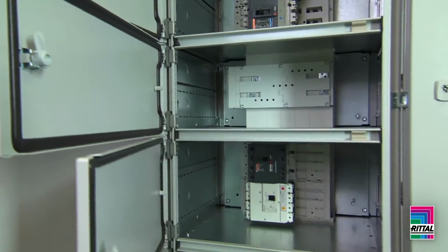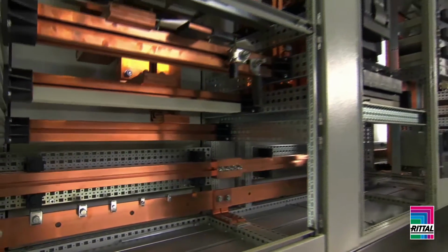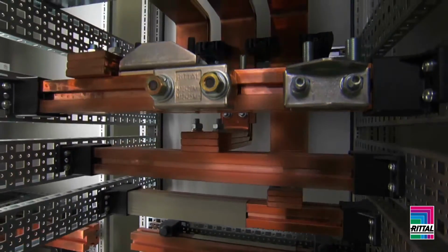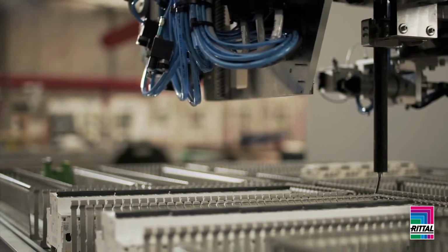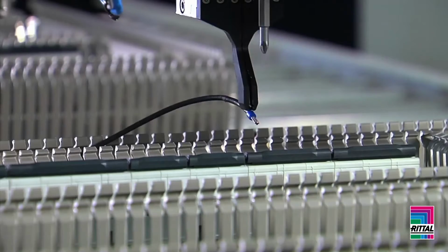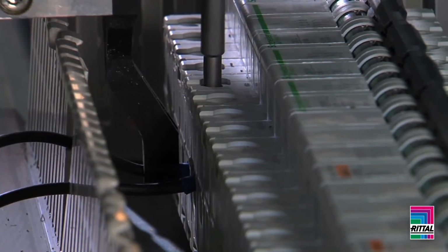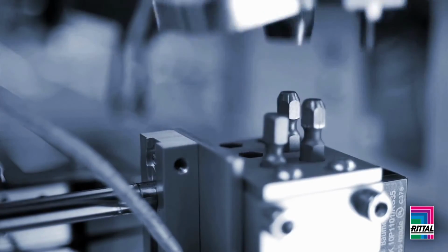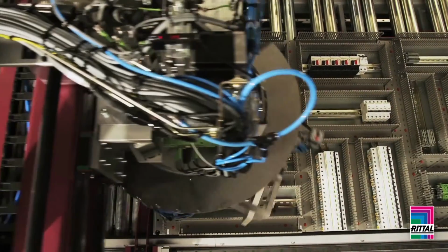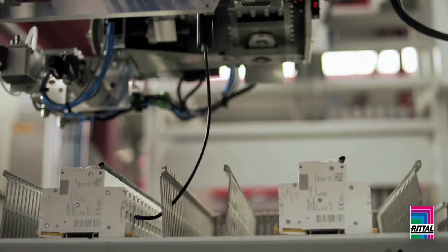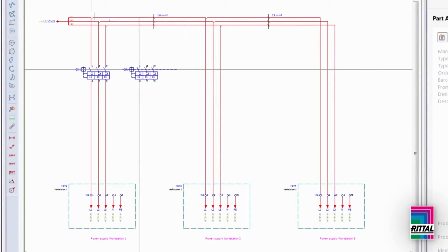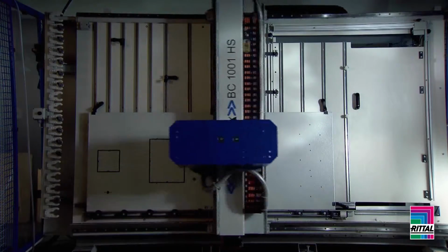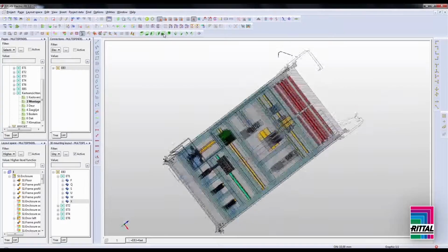Once the design is completed, a modular Rittal enclosure is selected for its ease in hardware and cooling systems installation. Adding custom holes and installing enclosure electronics is automated thanks to Kiesling's panel cutting and wiring machines. This interconnection simplifies the original design and enables automatic updating of the complete design if the first step ever changes. From wiring diagrams to custom holes, automatic updates tremendously decrease design iteration time.